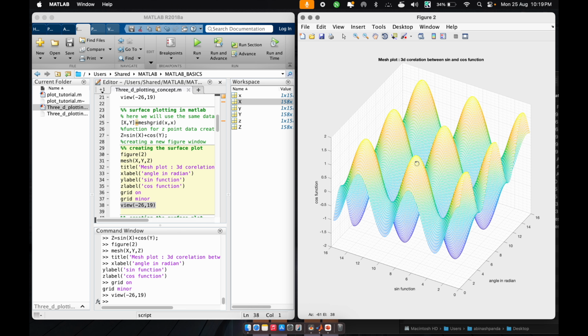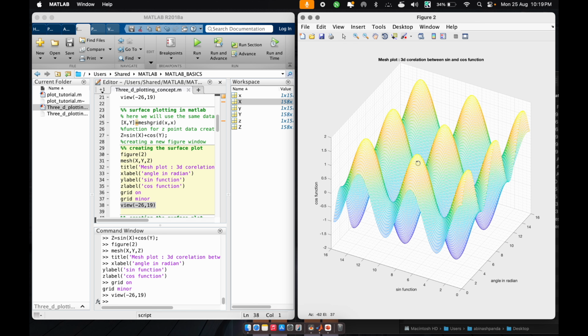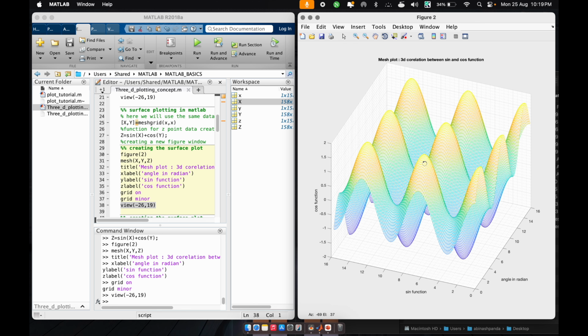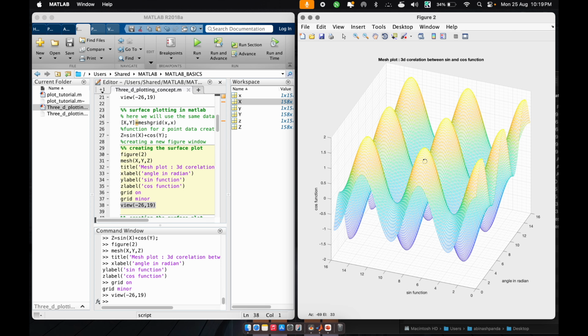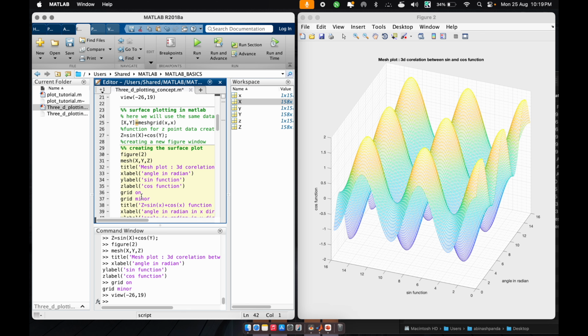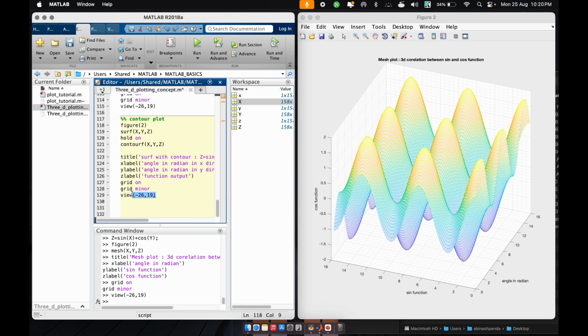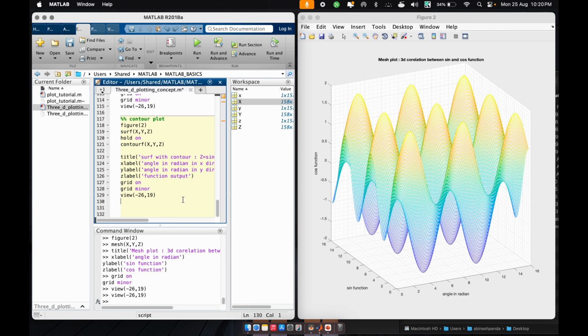And on the downside, you are able to see azimuthal, which is basically 61, and elevation, which is basically 38. If you want a particular view, azimuthal and elevation, then you can read that by having it in a defined way, and then you can use those two numbers so that it will adjust the view in your own way. So if I just right click, my view will change now. See? Yeah. So this is basically a mesh plot.